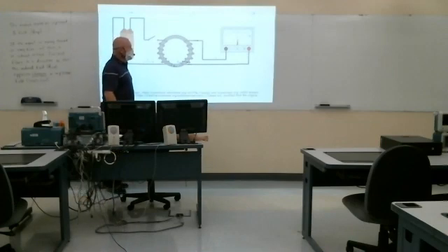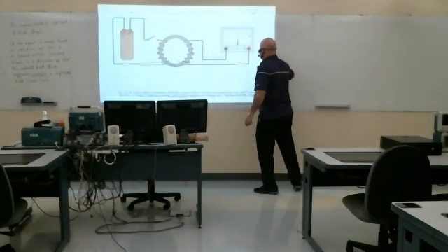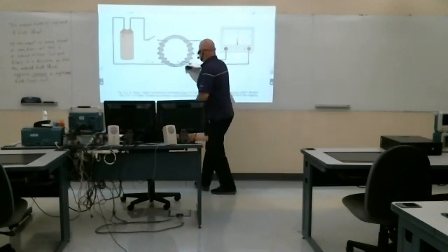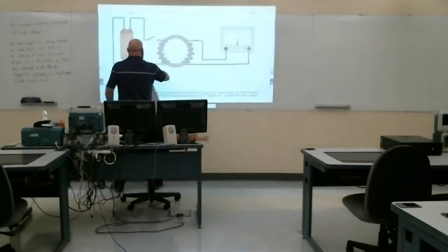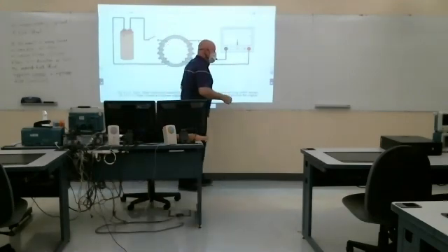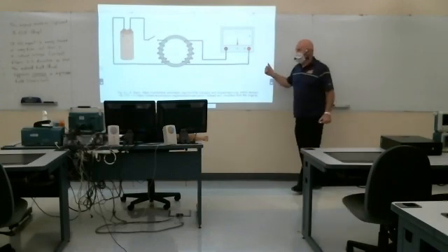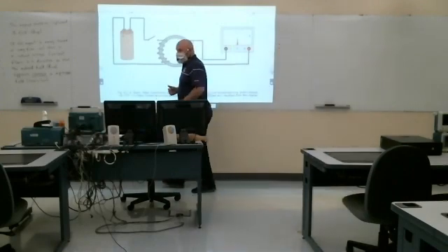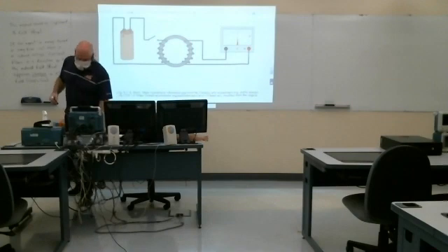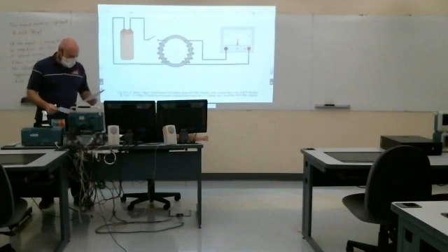And in that case, I get a negative voltage when I close the switch without changing the secondary coil. So all of this is important in determining the polarity of the secondary voltage. So understanding the right-hand rule is critical.